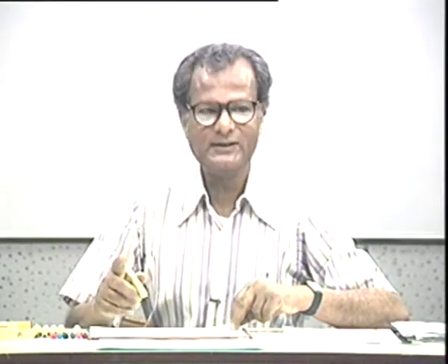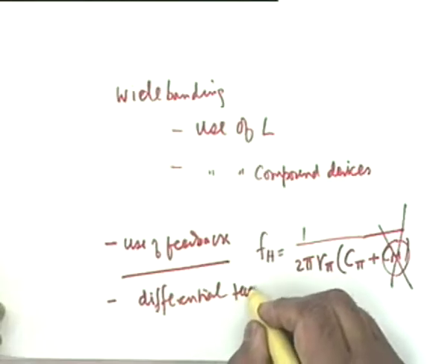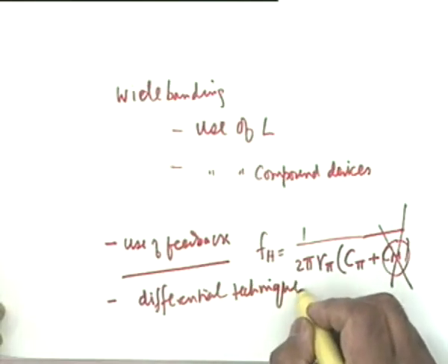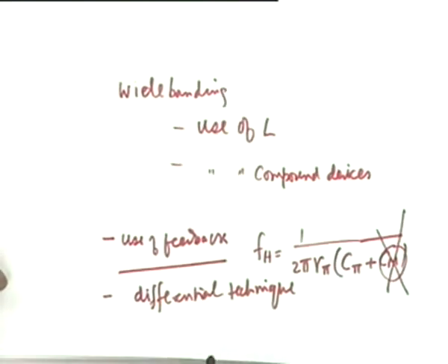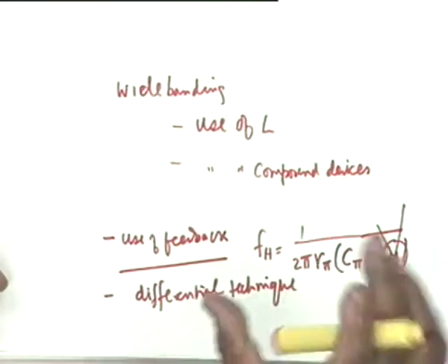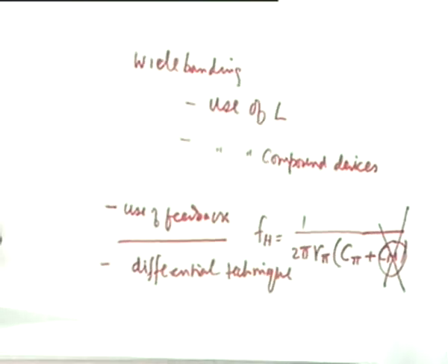Then we will show that the differential amplifier technique that is so popular in integrated circuits, op amp and every other circuit uses a differential amplifier. This differential technique can also be used for wide banding. So, differential technique. We will show this circuit later and make a detailed analysis.